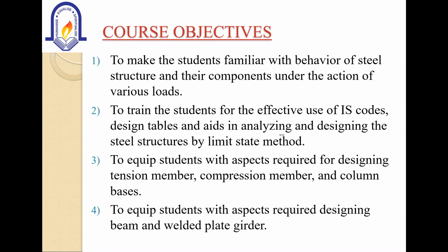And the next important load is your seismic load. So what is seismic load? Seismic load is nothing but the load because of the earthquake. When we are going to design the building to resist the earthquake effects, we are going to consider the seismic load. So for seismic design, there is one IS code, that is IS 13920, that you have to refer when you are going to consider the seismic load for the designing part.